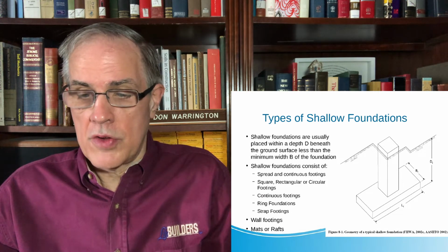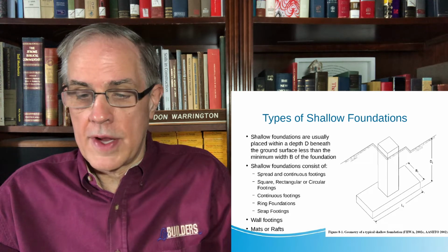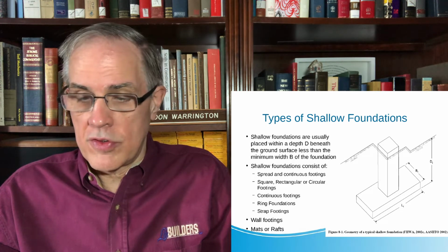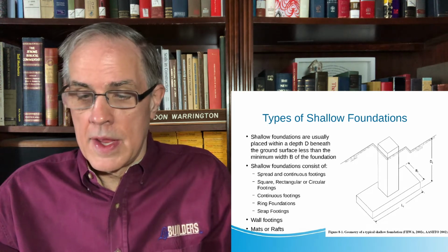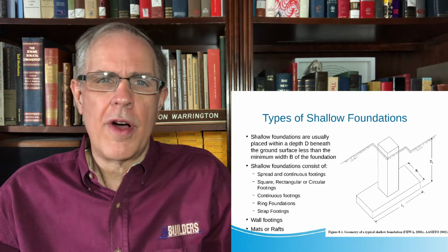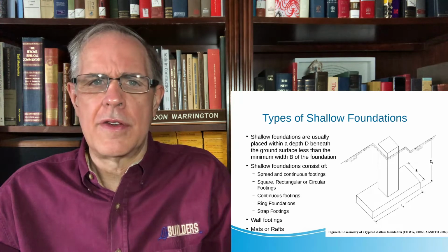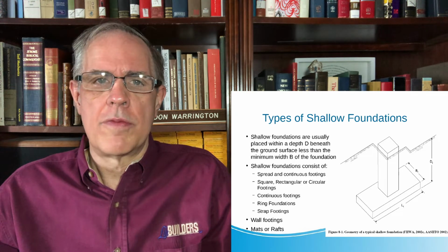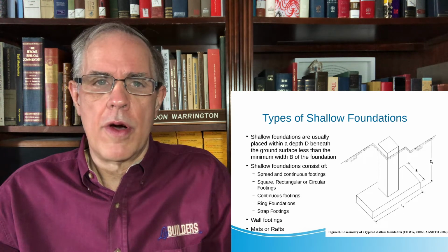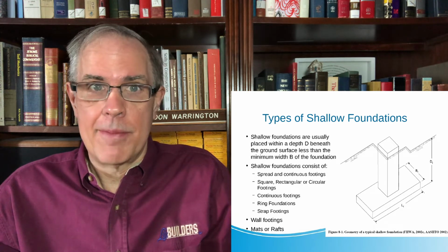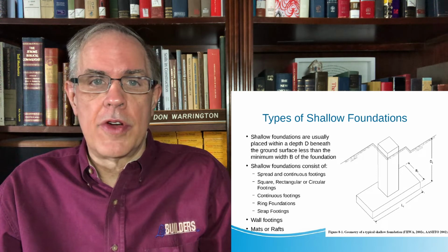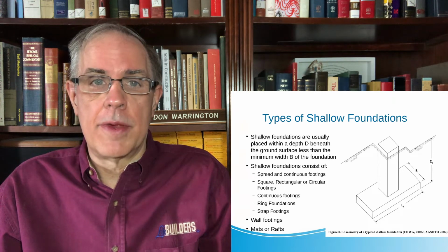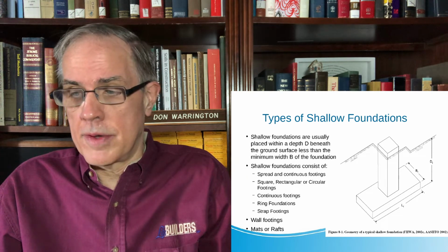There are continuous, square, rectangular, ring foundations, circular foundations, and strap footings. There are also wall footings. Wall footings are usually a continuous foundation which bears the load off of a wall continuously. And then there are mats or rafts, which are very large foundations where the flexibility of the foundation becomes an issue.